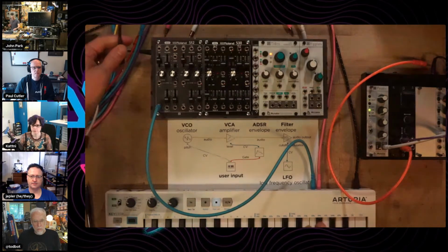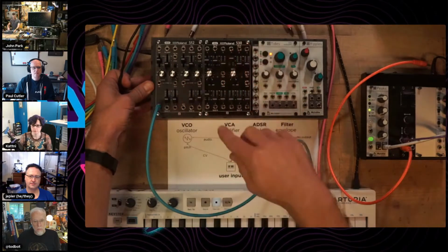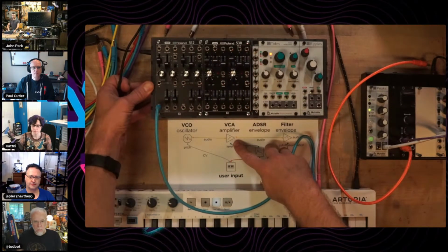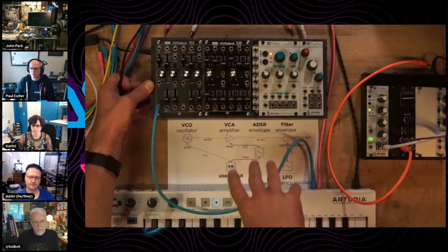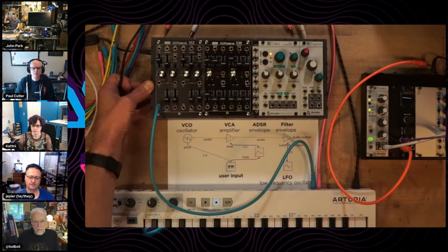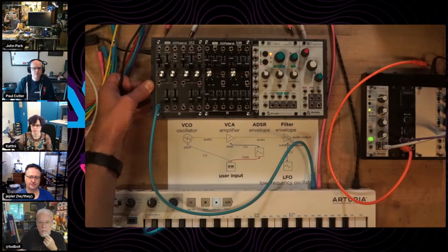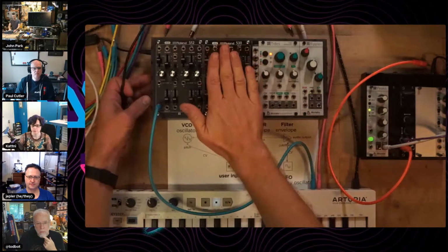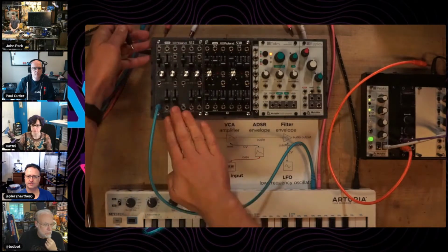So what we'd like to be able to do is listen to that oscillator after it has gone through what's called, somewhat confusingly, a voltage-controlled amplifier. It's actually more of a voltage-controlled attenuator. It doesn't really amplify in the sense of some other areas of music, like guitars, where amplification is really gone. These are really just from 0, it's off, to at its full volume at 1. Sometimes they have a little overdrive to them. But anyway, this is a thing that can essentially mute and unmute in gradations the sound coming from that VCO.